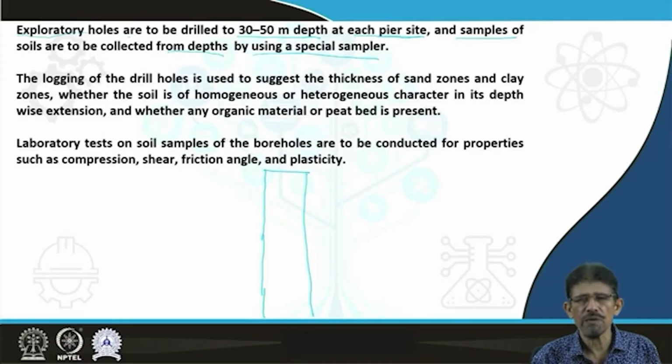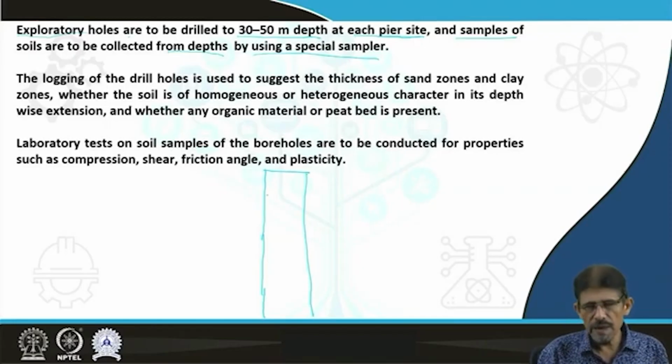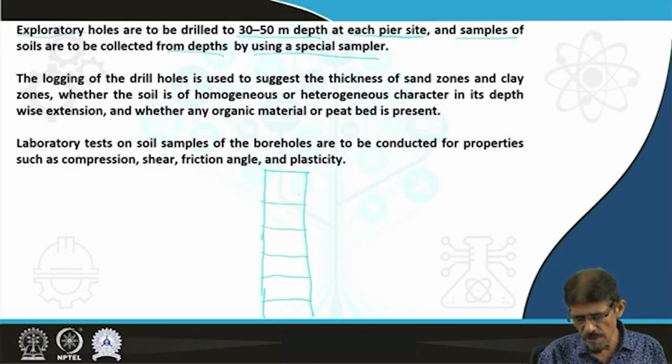In case of rocks, we characterize rock strata in view of rock mass characterization and evaluate the quality of the rock mass, and then the strength of rocks, modulus of rocks, and Poisson's ratio of rocks, and various types of modulus like secant modulus, tangent modulus, average modulus, bulk modulus, modulus of rigidity, etc. After estimating the different mechanical and geotechnical engineering geological properties,